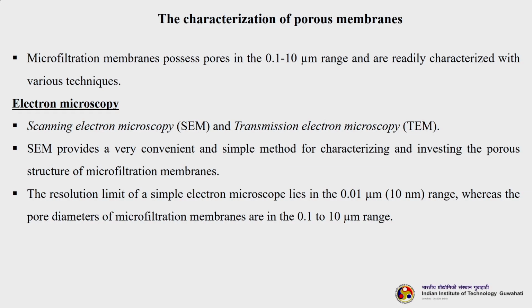Under electron microscopy we have two distinct techniques. One is scanning electron microscopy, another is transmission electron microscopy, SEM and TEM. SEM is a very convenient and simple method for characterizing and investigating the porous structure of microfiltration membranes. The resolution limit of a simple SEM lies in the range of 0.01 micron, that is the 10 nanometer range, whereas the pore diameters of microfiltration membranes are in the 0.1 to 10 micron range.